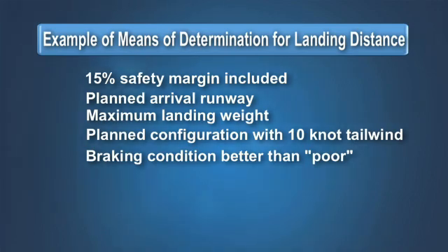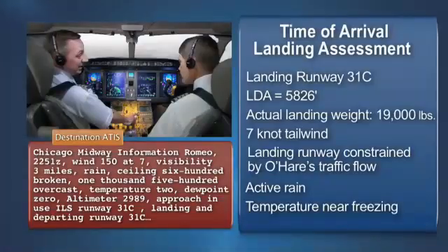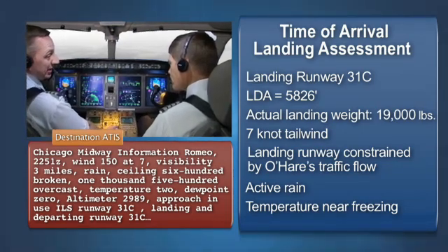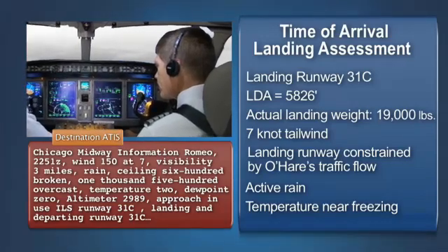Your assessment at the time of landing may be as simple as verifying that the landing would be conducted within those parameters. This landing distance assessment should be accomplished as close to the time of arrival as practical, taking into account workload considerations during critical phases of flight and using the most up-to-date information available at the time.